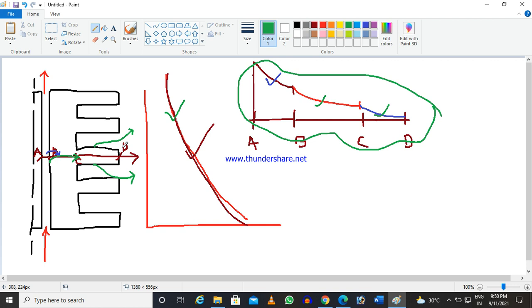If the temperature of the object is high, the heat will be evacuated at a higher rate. If the temperature is low, then the convective heat transfer rate will be less. If flow is more, your convective heat transfer will be more. So definitely this area is natural convection.